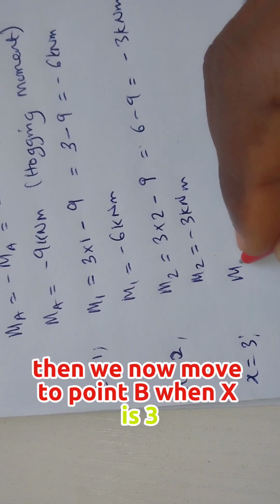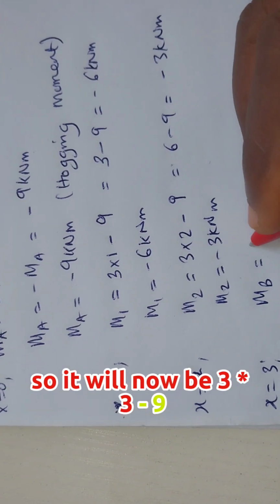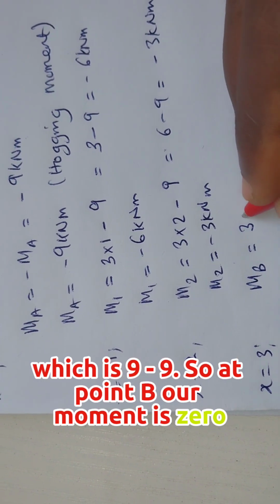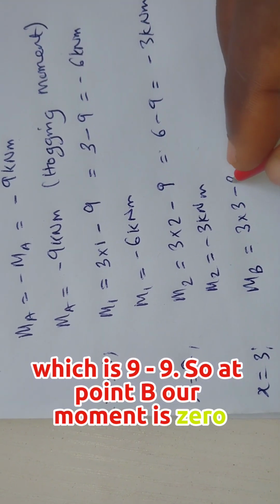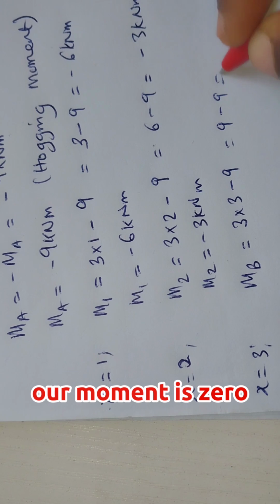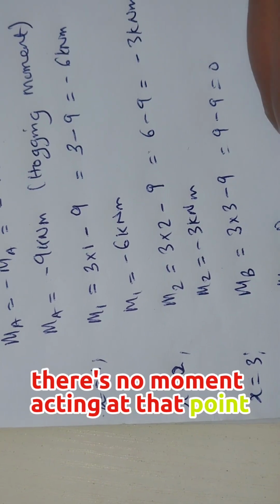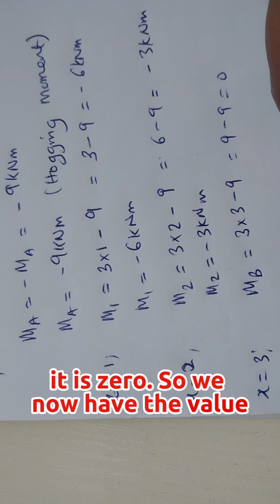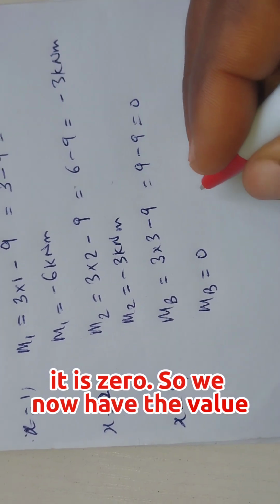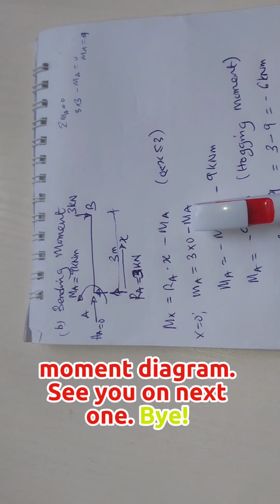Then we now move to point B, when x is 3. So it will now be 3 times 3 minus 9, which is 9 minus 9. So at point B, our moment is 0. There's no moment acting at that point. So we now have the values, and with this, it will help us to draw the bending moment diagram.